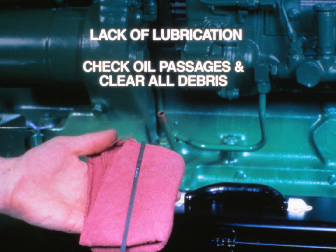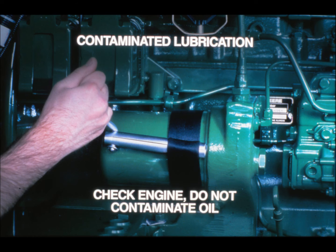Lack of lubrication failures result from engine problems or improper engine operation. If the turbocharger inspection shows a lack of lubrication failure, the engine should be checked to determine the cause of the loss of lubrication. If you determine that operation is the problem, discuss proper procedures with the customer. Contaminated lubrication failures require inspection of the engine. Often oil contaminants are a sign of an undiscovered engine failure. Extensive repair may be required.